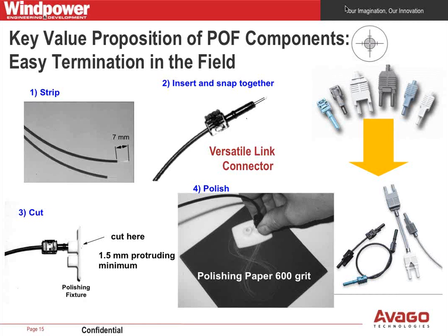So this just gives you a quick idea of the concept of easy termination. This is an example for POF, as it says, key value proposition of POF components. POF for us means plastic optical fiber. So this is for our shorter length distances, mainly you'd say somewhere in the vicinity of 50 meters, basically down to say 1 meter or so.